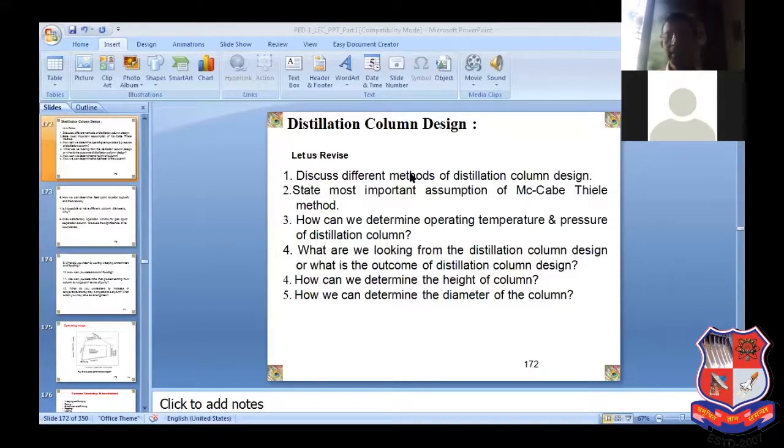Fine. We are saying that, and again your delta T depends on the capacity. I can increase the temperature, like you can say that yes, if I go for use of a cooling water, your 35 degrees centigrade is a vapor temperature, when it gets condensed at 35 degrees centigrade. So what will be the water temperature maximum you can have? Normally we are recommending that delta T LMTD, delta T MTD at any circumstances should not be less than 10 to 15 degrees centigrade. Fine.